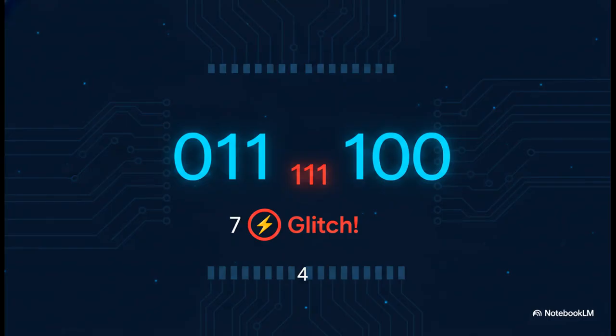Okay, let's look at a perfect example. The jump from the number 3 to the number 4. In binary, that's going from 0, 1, 1 to 1, 0, 0. Now look closely. Every single bit has to flip. And here's the thing about the real world. Nothing is perfectly simultaneous. Those bits don't all change at the exact same nanosecond. So what if that first bit flips just a fraction of a second early? For a tiny, tiny moment, the system might read 1, 1, 1, which is the number 7. And that's the glitch. It's a temporary error for sure, but it can be a really dangerous one.